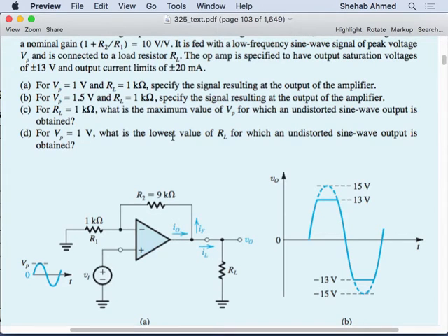So they give you some examples that are very straightforward, so I will not go through them. They just calculate the current. We derived the currents in these circuits, right? There's the inverting amplifier, the non-inverting amplifier. We know how to derive the values of the currents. So just derive the value of the current and calculate the current here. You know the output voltage divided by the resistor, calculate the current here. Make sure that they're both less than the value of the rated current of the device.